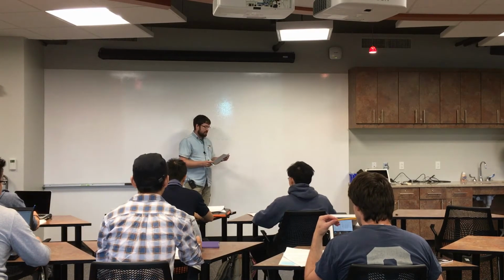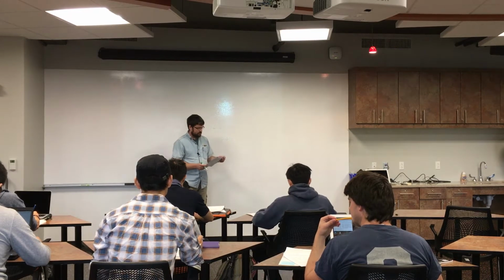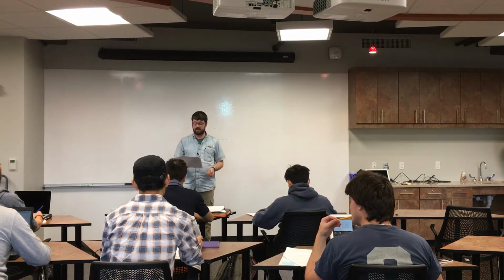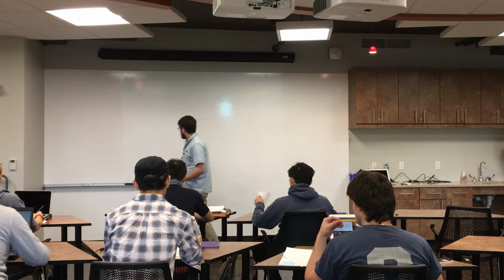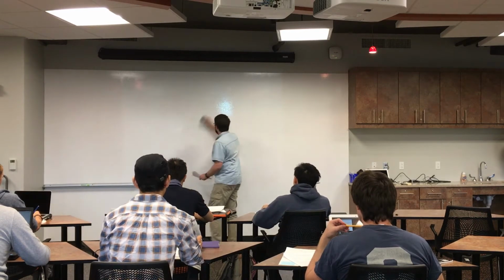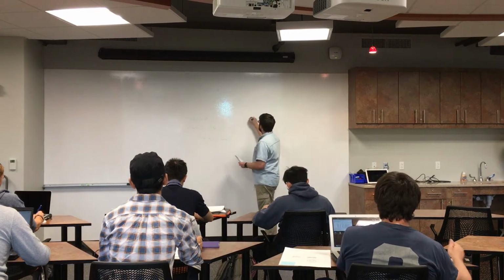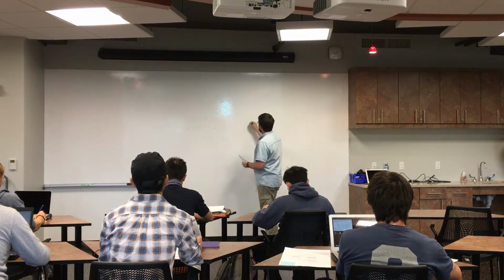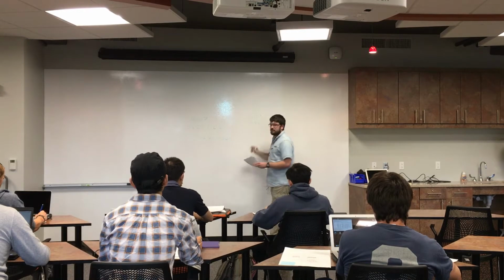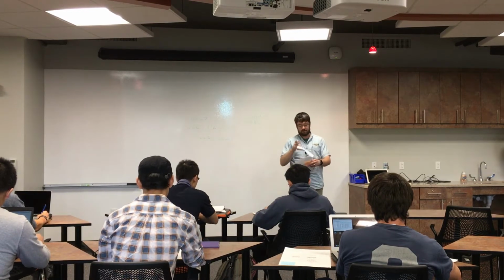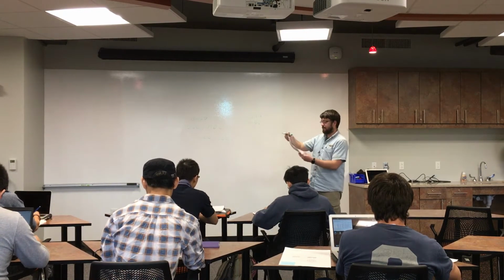What 2 values in the table would be easy to use as troubleshooting characters when looking at the signal on an oscilloscope or a logic analyzer? What I was looking for, that works well, was AA and 55. So if you look at their binary representation.